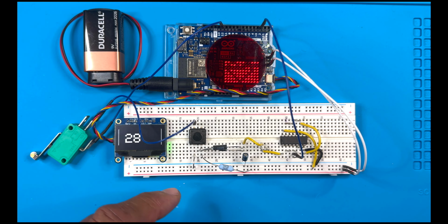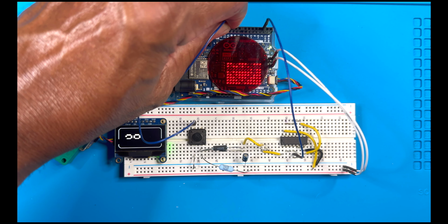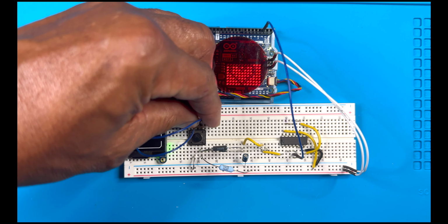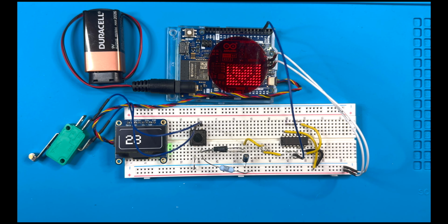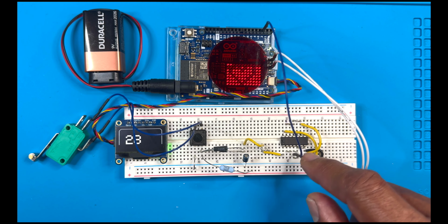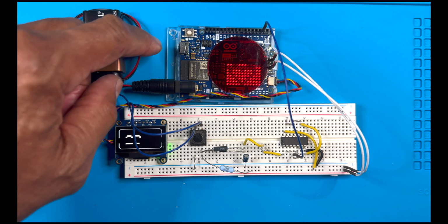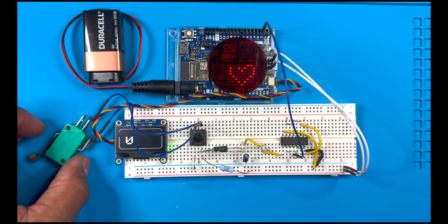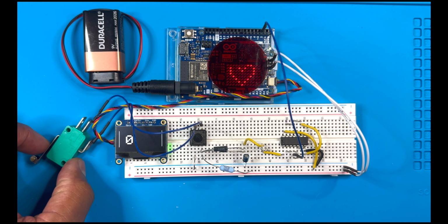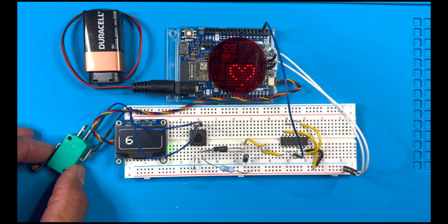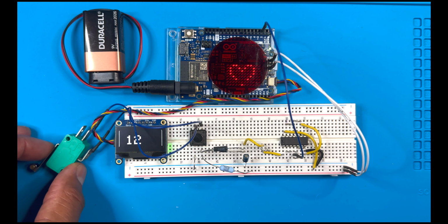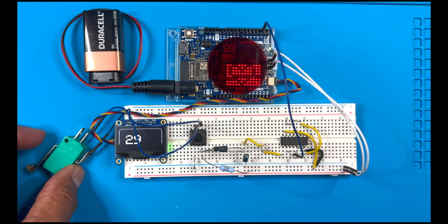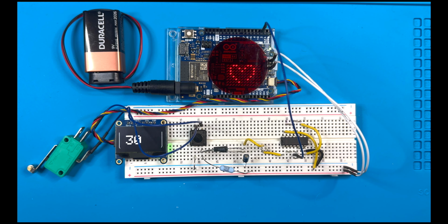So now let's switch this over and go through our RC network and Schmitt trigger, and see if we're hooked up on this side correctly into our Schmitt trigger output, generating an interrupt. A cycle of 10 should give us a count of 10. Let's go. 1, 2, 3, 4, 5, 6, 7, 8, 9, 10. Okay, that's working.